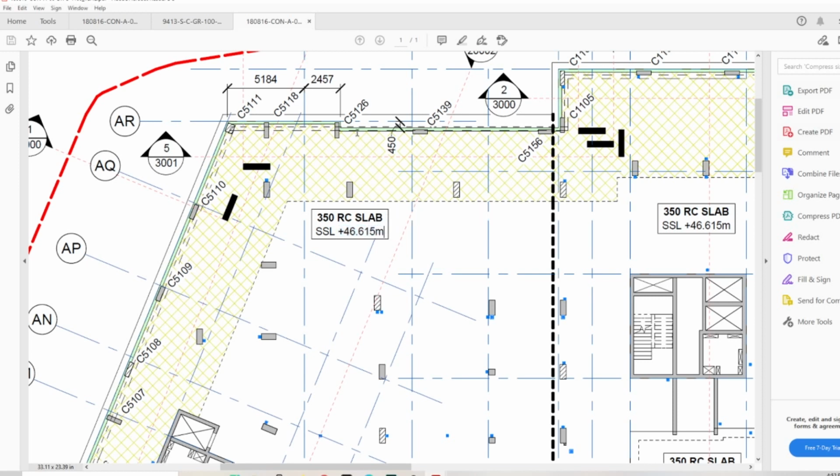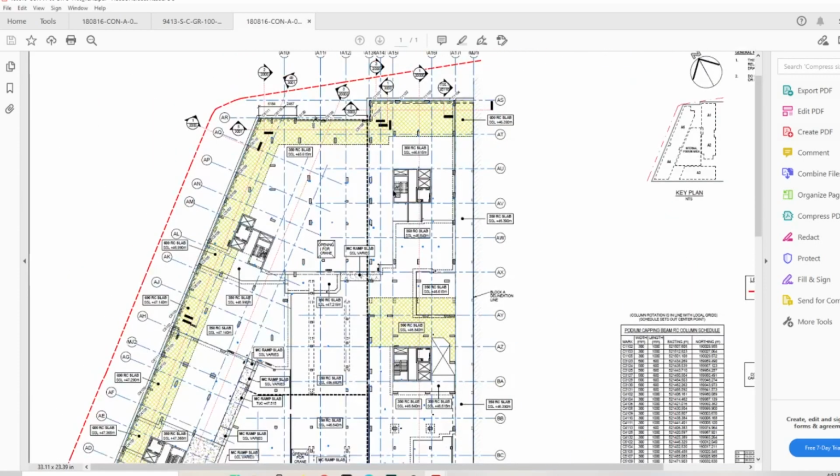So once the slab is going to be meeting the capping beam, we need to make sure all the starters are going to be at this level plus the cover for the reinforcement. So yeah, that's it. I would say we got all the information for block A.